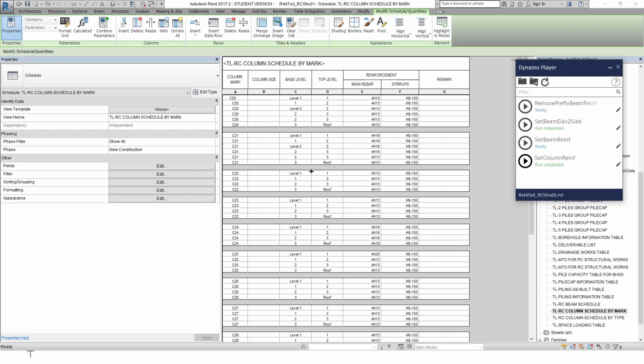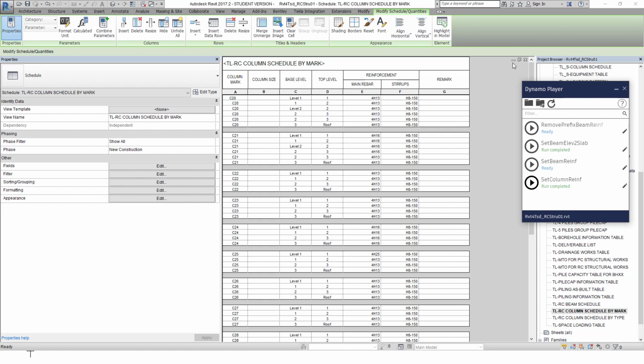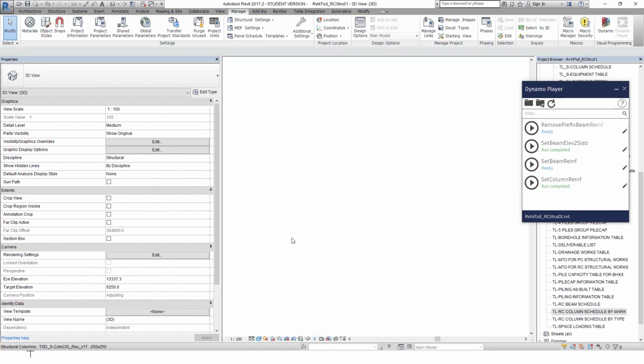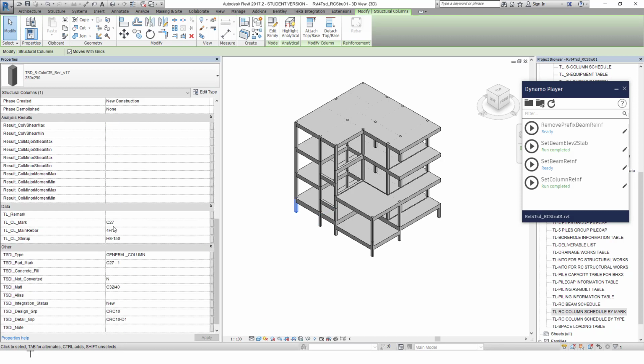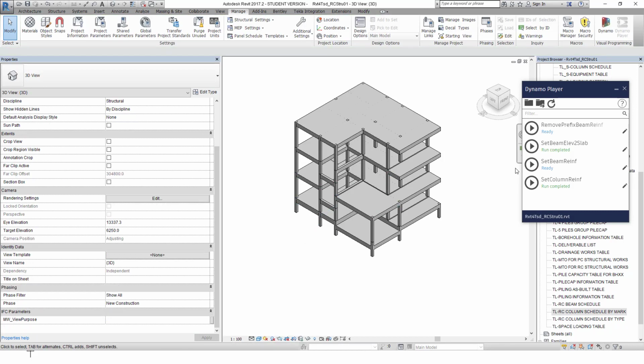Actually, it's not that they appear automatically. What the application does is transfer the rebar information from the TSD to our Revit parameter. Whenever the model is updated from the TSD, they will give it to us as a .cxl file. Then we have to rerun the code to update our Revit information. So this is the way that we do it.